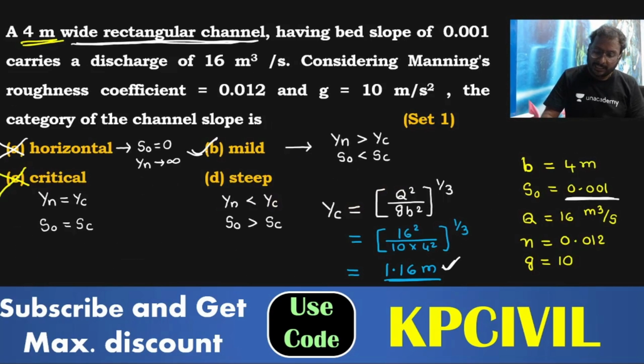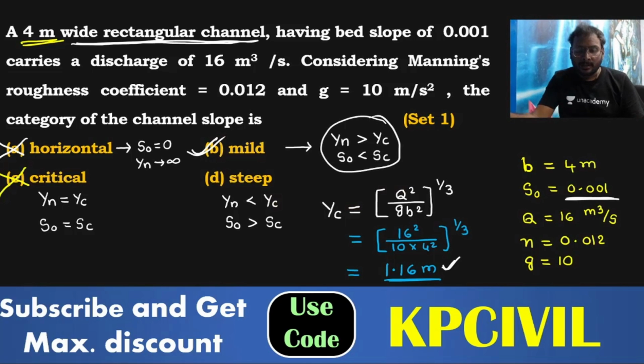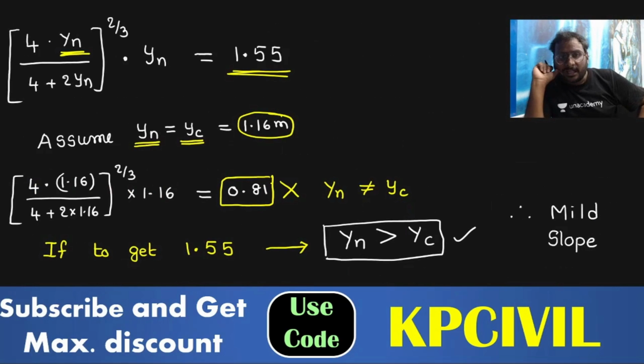Mild slope, now yn is greater than yc. To get the final value of 1.55, yn must be greater than 1.16. Then only you will get 1.55. Yn is greater than critical depth, so it is a mild slope.